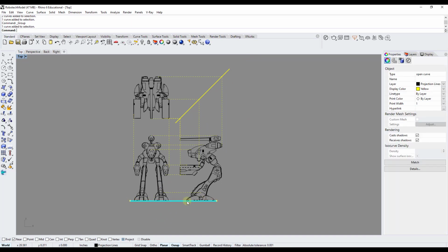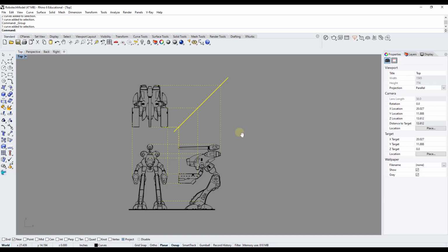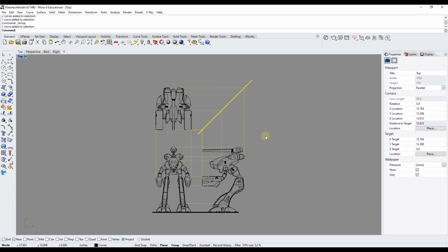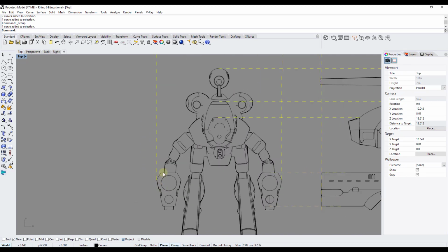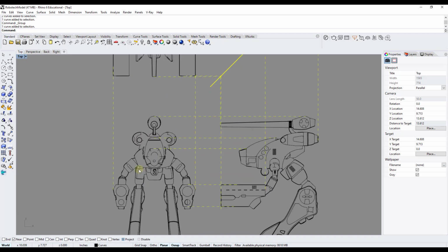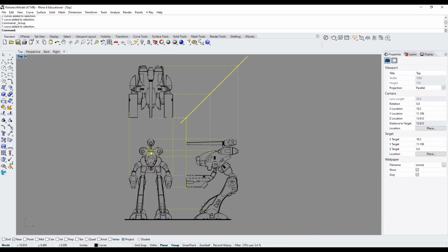This one, instead of being a yellow color, I go back to my display color and I switch it back to black color, like so. Okay, and that's how I like to play with my different line thicknesses. And you can imagine for the contour lines, if you manage to join all these curves into one, for example, you can make the silhouette thicker also. But Make 2D also offers the option to make the silhouette thicker than the inner curves also, okay?